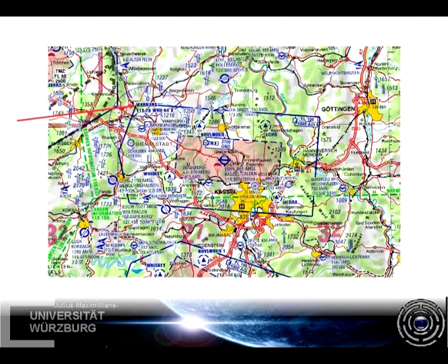This is the name of the station, Warburg. The frequency of it is right below the name, 113.70 MHz. If you tune the station into the receiver, you should be able to hear the identification Morse code, which is WRB. To make it convenient for pilots who have not mastered Morse code, the beeps are depicted visually also. This way, the pilot can check that he is receiving the intended VOR station.